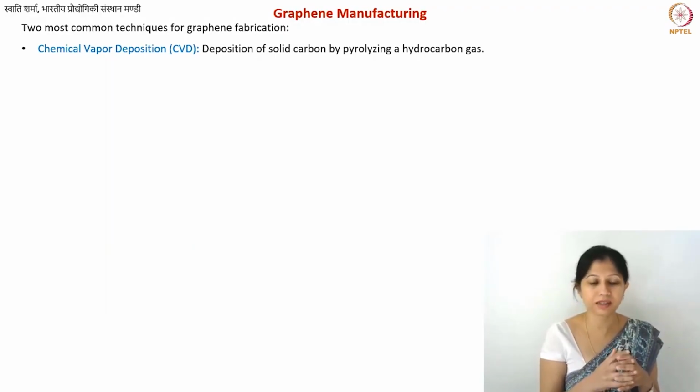There we discussed the enthalpy of methane or any other hydrocarbon, how the enthalpy of formation changes with temperature, and at which temperature you then have the optimum deposition, given the solubility of carbon inside your metal. That is your optimum deposition temperature. So all of these things are also valid for this particular process. I'm not going to repeat them, so go through that lecture.